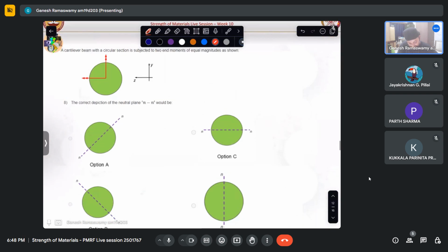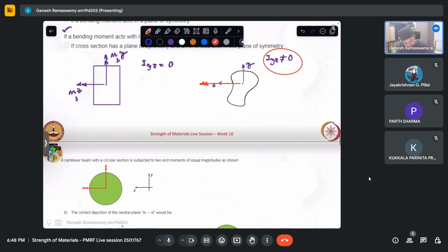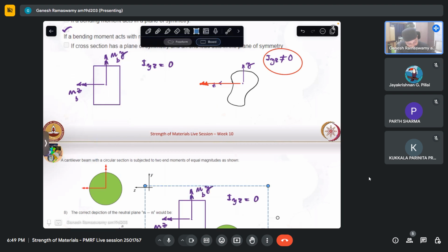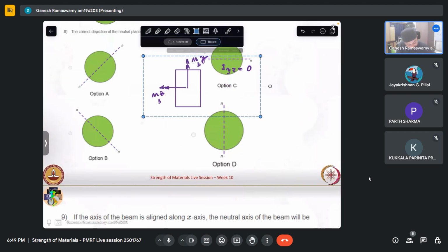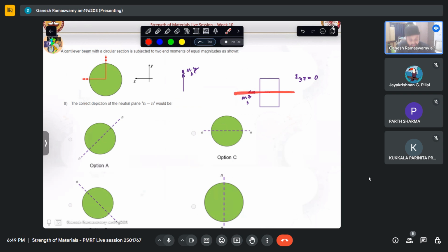Now, in such a case where there is unsymmetrical bending, our neutral axis will no longer be parallel to our axis, as we were seeing in the earlier cases. In the absence of this, this would have been my neutral axis where sigma x is zero. This will be in maximum tension, this will be in maximum compression, which when I draw it sideways, will look something like that.